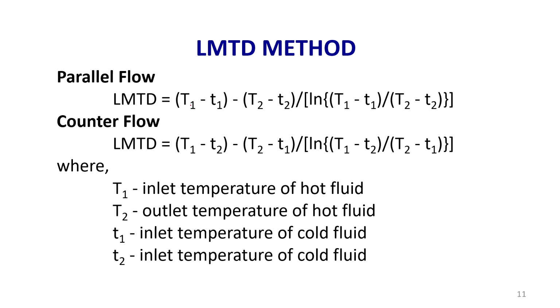LMTD, this is capital T1. Here I am taking capital T for the hot fluid. Until now I was using capital T for cold fluid and small t for hot fluid. I have just changed it here, because these terminologies I have followed as per the heat and mass transfer data book. So, capital T is the hot fluid and small t is the cold fluid. This is very important.